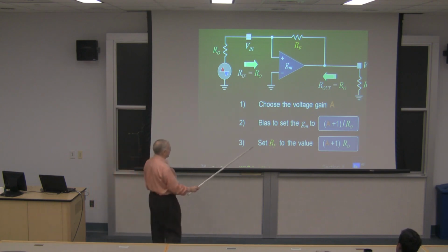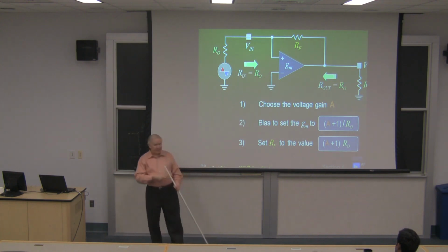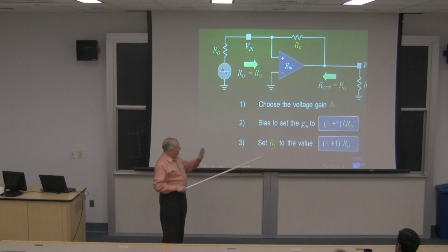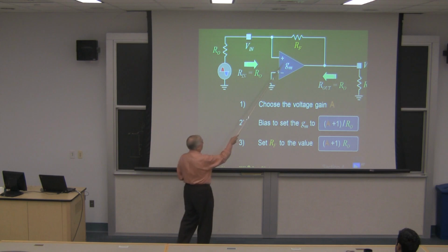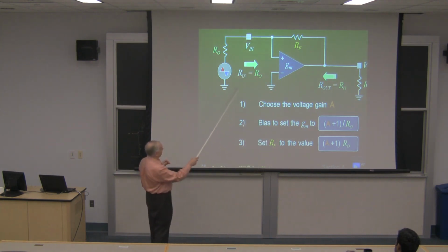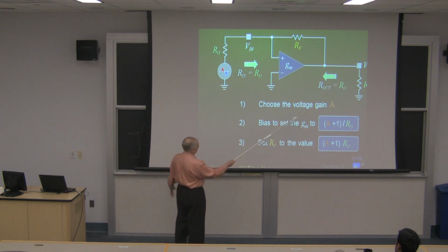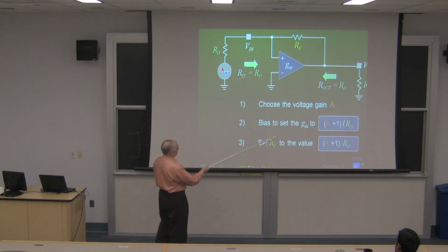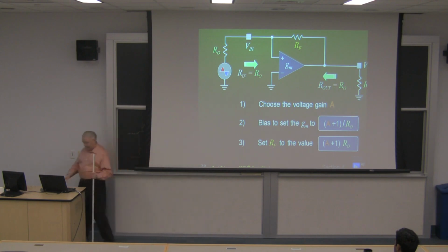Clearly, this is a little bit lacking because we haven't yet said anything about the voltage noise at the end of the GM. But at this point, I am asserting that this configuration, by a previous demonstration, is the lowest noise configuration, where the matching is done by feedback. And now I'm not talking about noise anymore for a moment, I'm talking about how you design this amplifier for a given gain. So you choose the gain, choose the bias, and choose the feedback resistor, and you're all done, you can go home. Or if you're more interested, you can keep going and figure out more funny things about circuits like this.